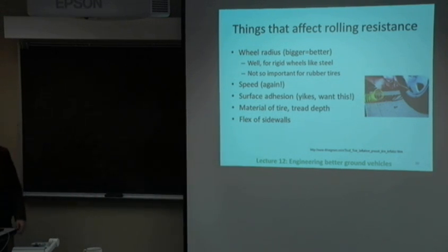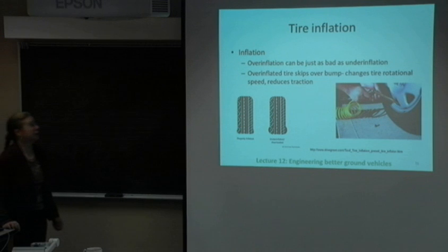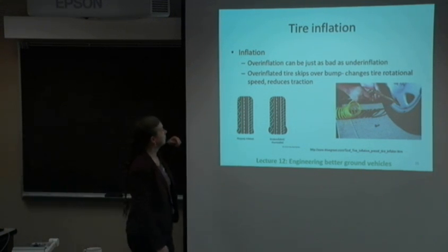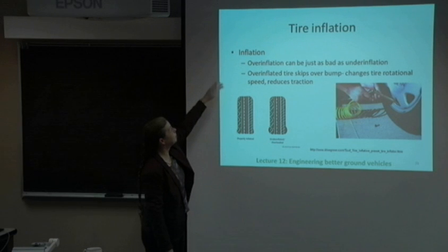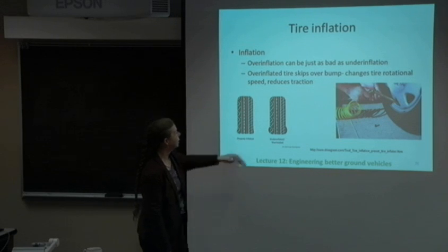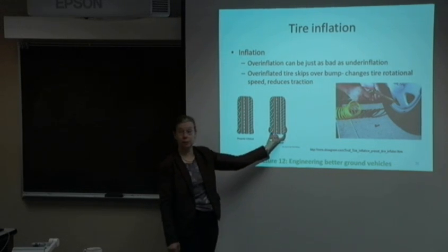Maybe it's just styling. Tire inflation makes a difference, and actually overinflating is just as bad as underinflating. An overinflated tire will skip over bumps and it'll change your tire's rotational speed, so there's some energy there, and it also reduces your traction. Underinflated, of course, you're deforming it even more.